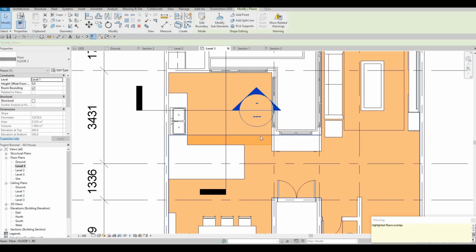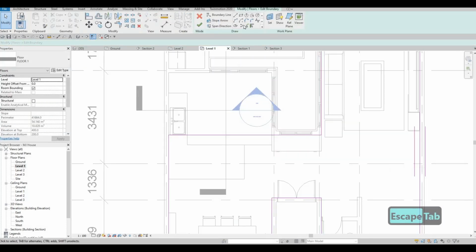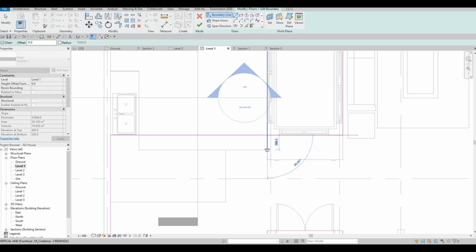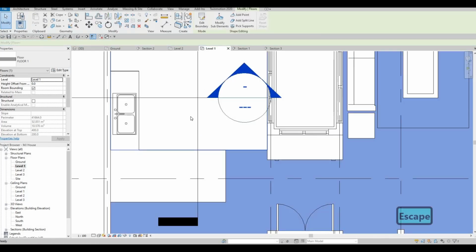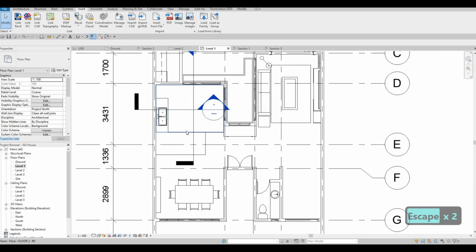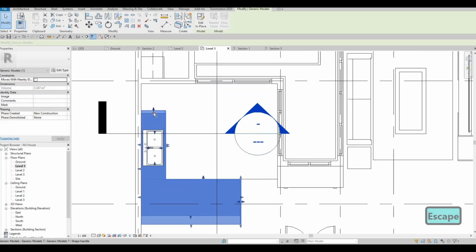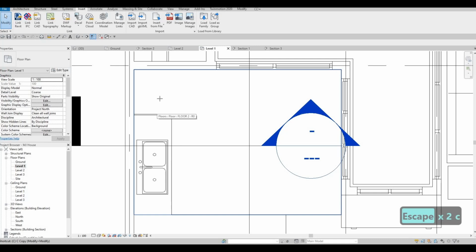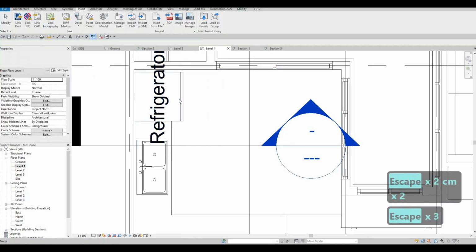And then the error is because Revit noticed something there, that there's an overlap. And then we could just trim it off like so. So that one is fixed in terms of overlapping, and then we could just extend this one a little bit more. CM on this. Let's see how it looks. We could just leave it like that for now.